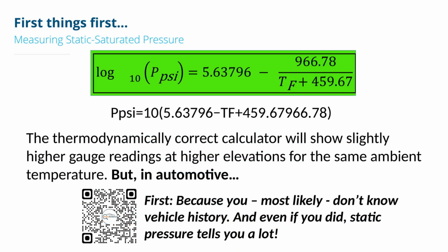No matter which loop design a vehicle uses, expansion valve, accumulator, dual evaporator, or heat pump, the static pressure check is always the first step in evaluating the refrigerant system's overall health.